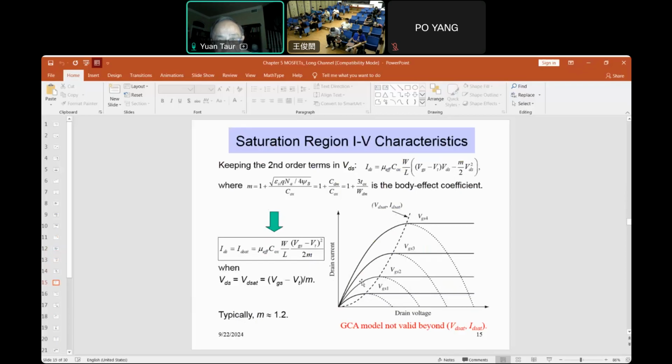Okay. So at low drain voltage the current is linear, the first term, and then the second order term is negative, which means that it bends over. This is actually parabolic, with the apex given by the saturation current. And so for this parabolic curve, the apex can be solved.